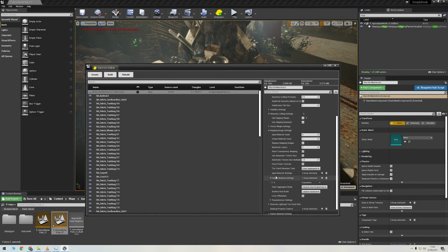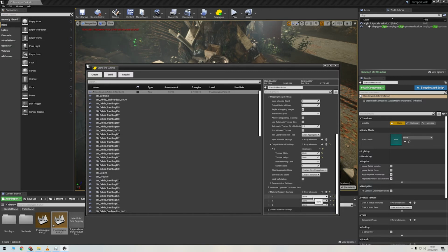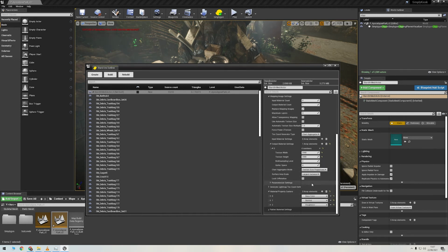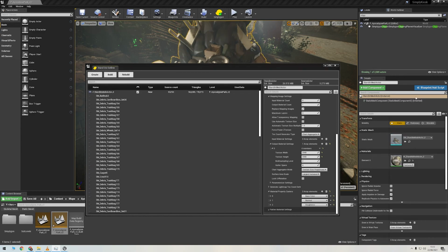Finally, in the Mapping Image settings, we can adjust the output texture size as before. I'm going to set this to 2K, which is 2048 by 2048. And then finally at the bottom, make sure you add the materials you wish to cast. I'm going to cast base color, normal and roughness. Great, that should be everything. To start the processor, click Build. And there we go, it's done.